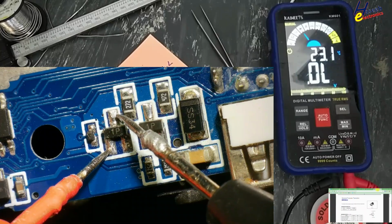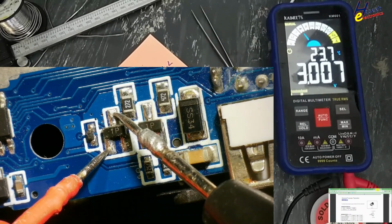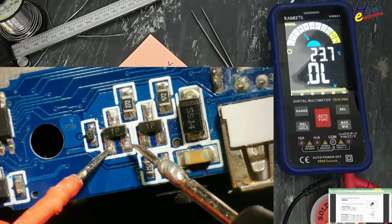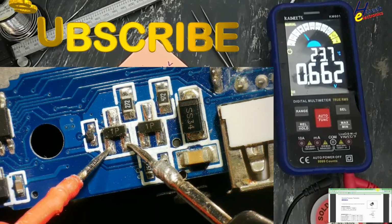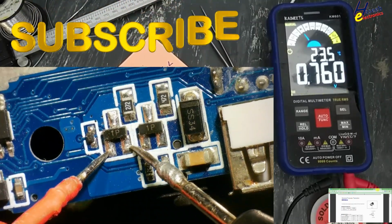0.663, 0.658. This value is low, that means it is collector, and this value is high, it is emitter, that means it is an NPN transistor.